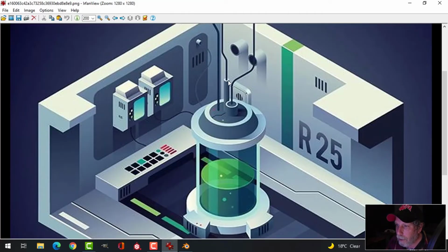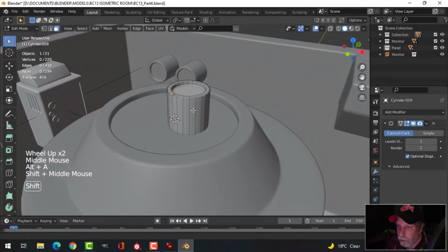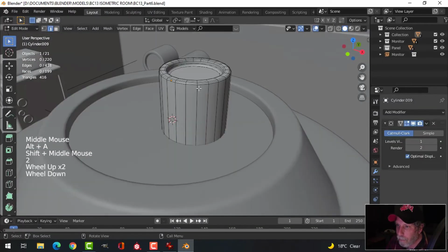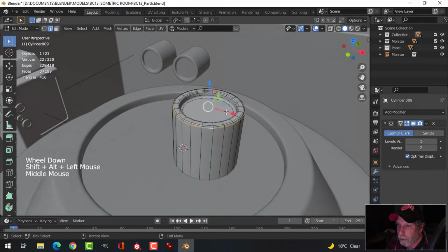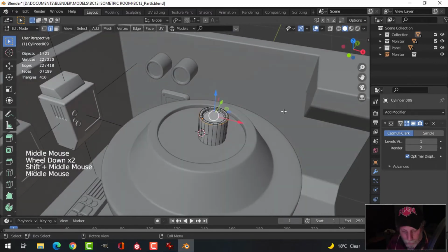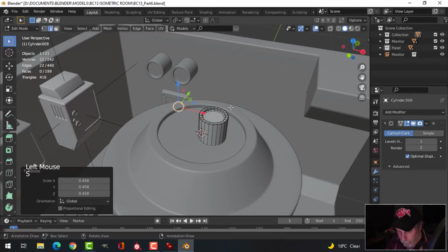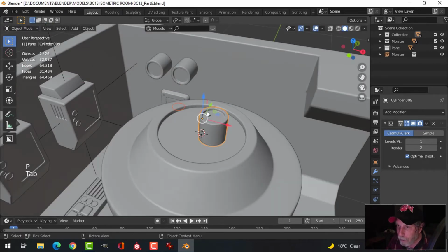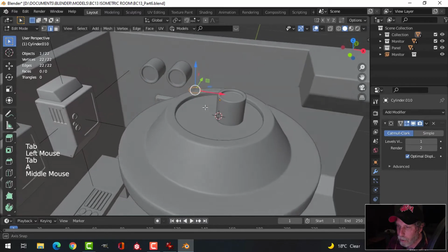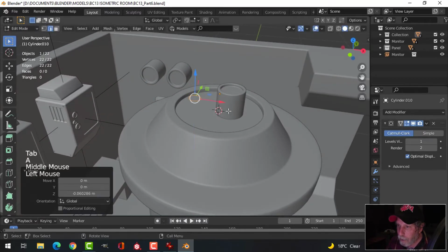This piece, I guess, doesn't indent like that one, so I want to make another circle, so I might as well just grab a circle, Shift Alt to click that one. I'm in edge selection for this and go Shift D to bring it out, S to scale it down, P, separate by selection, so it's a new object of its own. Let's say we have something like this.